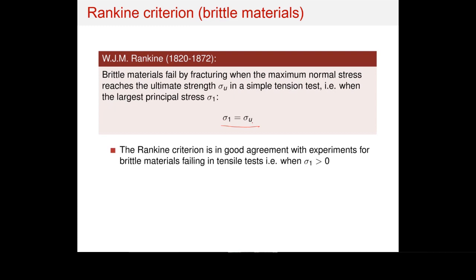Okay, so as I said, this is quite intuitive. This is kind of the most obvious thing to do. But there will be scenarios where this is not going to describe the behavior, because usually shear and normal stresses are active together. They work together, especially when we don't have very simple loading cases. So if you have the axial load case, well, you don't have any shear, or you have some shear, but this is not going to affect the critical behavior. But once you start to get into complex loading types, then in this case, this is not going to work. So you need to think of something else.